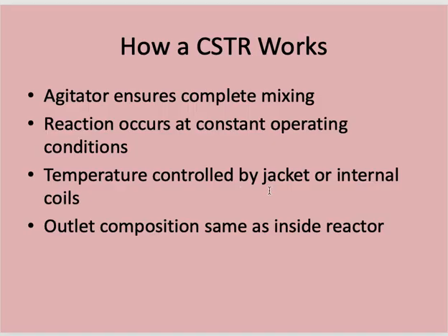Temperature is controlled by jacket or internal coil. So this idea we will see through the charts, that you control the temperature of the reactor by controlling the coil outside the reactor or by some internal baffles. Outlet composition is the same as inside the reactor.